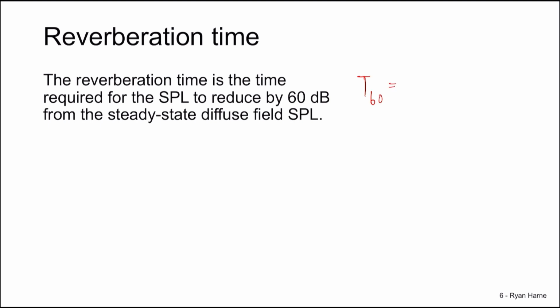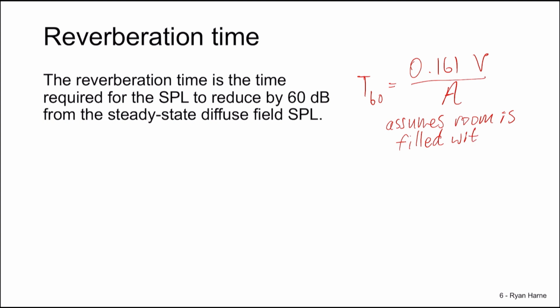This reverberation time is equal to 0.161 times the room volume divided by the room absorption A. This assumes the room is filled with air, which is very likely given the practical use of this reverberation time.